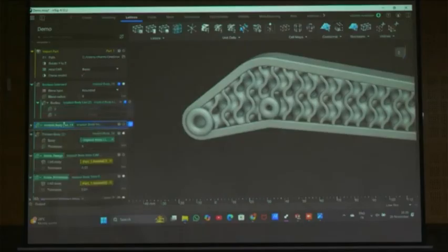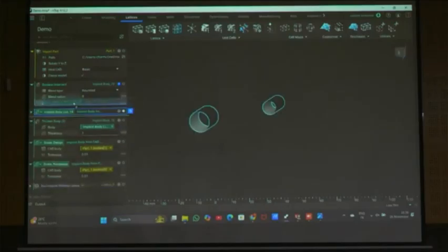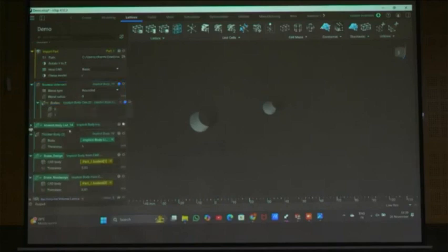And see, this is not even moving. Why is it not moving? Because these are two separate bodies, right? So the best way to show this, I am deleting this one. Why will I say it? See, I will delete this one. I will take this as a single body, and I will do the Boolean union there. Sorry. See, here you can see three bodies are there. 1, 2, 3. Three faces, three bodies are there.